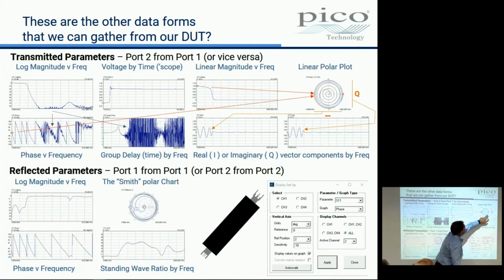So this is a linear polar plot of the same information. This is the magnitude of a vector, this is the phase of a vector. Let's put it on a polar plot, and with the circle at 0 and the circle at 1, that maps to a circle there. So at very low frequency, no phase shift, gain of 1, there it is on our polar plot.